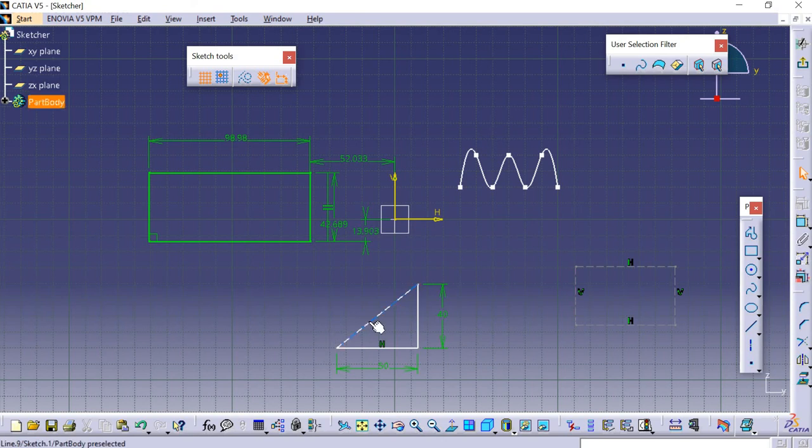And when we had constrained this line to 120, it had turned red, which means it's an inconsistent element. So at least one dimension value needs to be changed. This is also the case when elements are under constraint and the system proposes defaults that do not lead to a solution. We know that this line is not 120, so because we had given it as 120, the whole element had turned red, which means it's an inconsistent element. So once we delete that and constrain it to its value 64, we can see that it is white again.